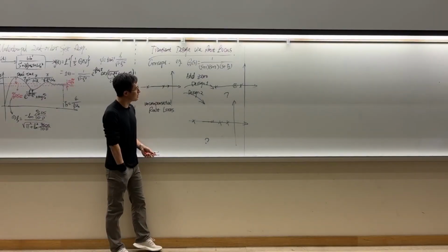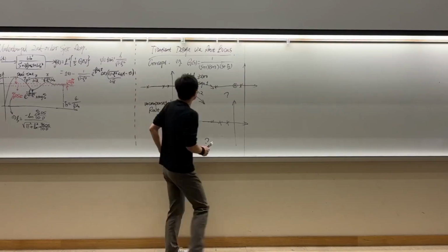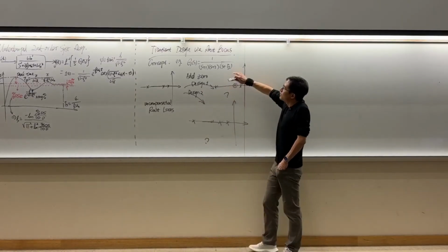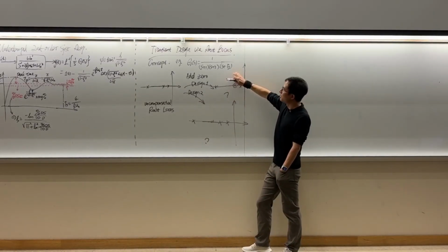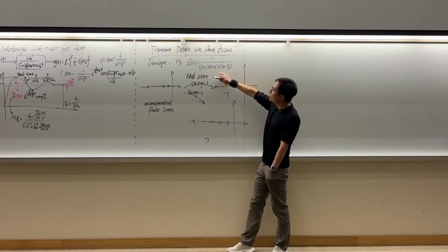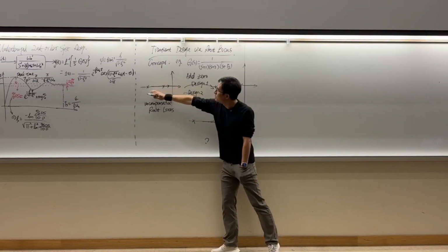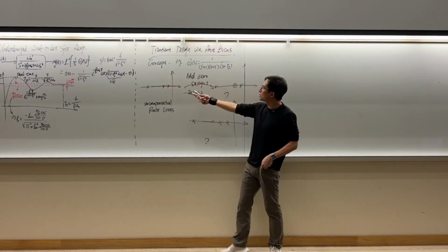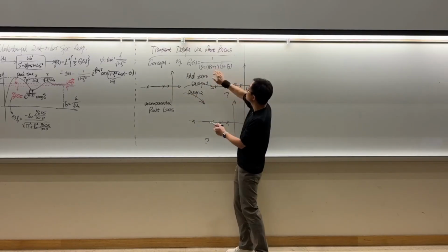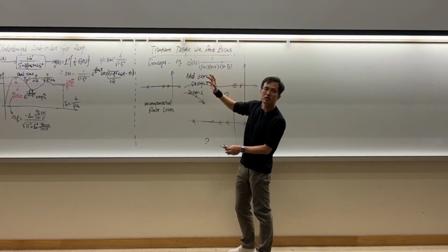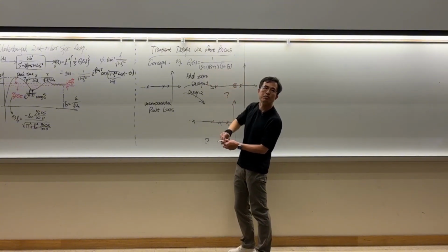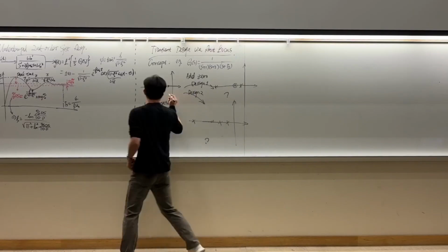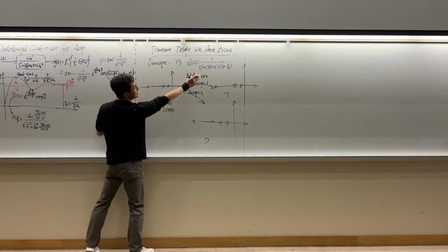Today we're going to do some actual control design using root locus as a core technique. Over here, I have an example that I asked you to think about. Suppose I have an open loop system with a pole zero map like this. You can draw the root locus if this open loop system is put into simple feedback control, proportional control. The root locus is going to be like this.